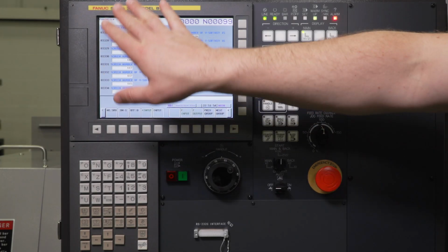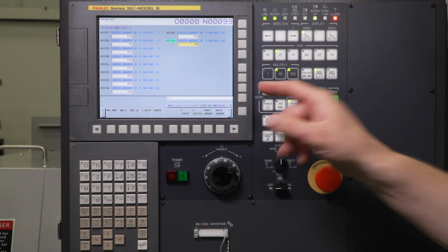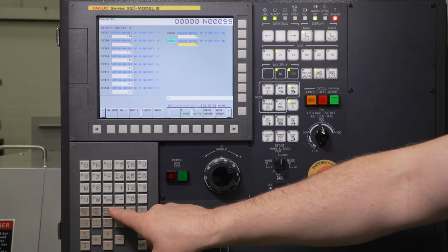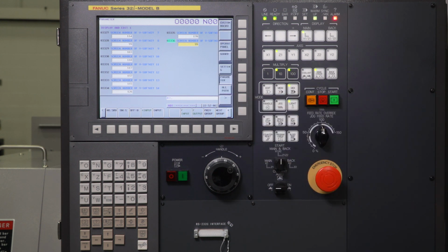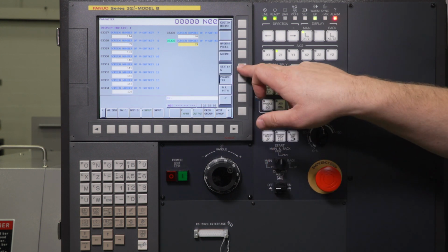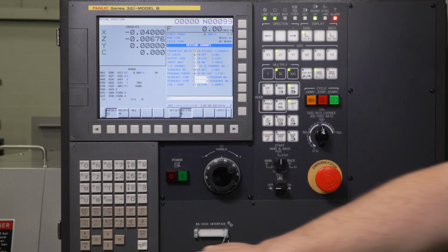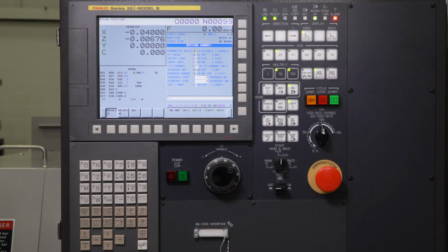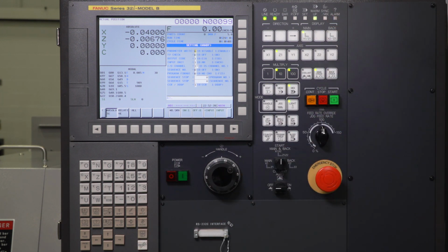So when you're all set, getting your shortcut screens labeled the way you would like, you need to go back and turn your parameter write enable back off to get rid of those alarms. So we're gonna go ahead, actually we can use our shortcut menu here. We can go to our settings screen. That's gonna bring us right to handy screen, which is our settings screen. Parameter write, we're gonna make this 0 input, and then we can press reset, and our alarms are now gone, and we're all set.